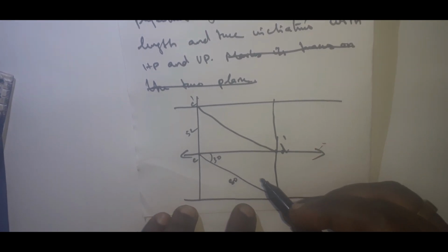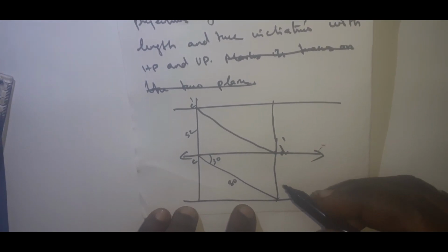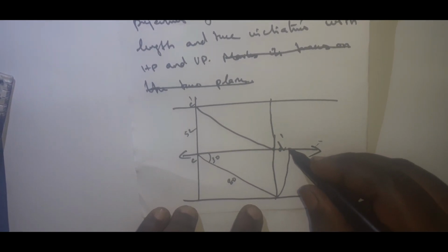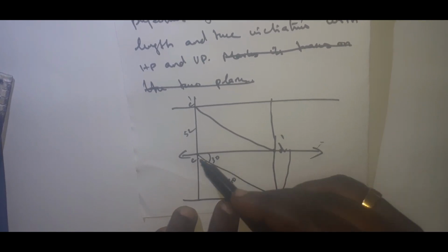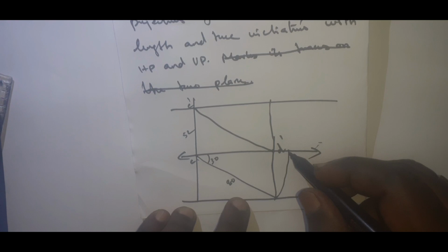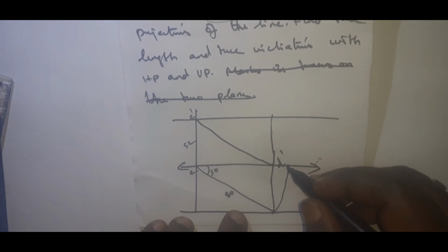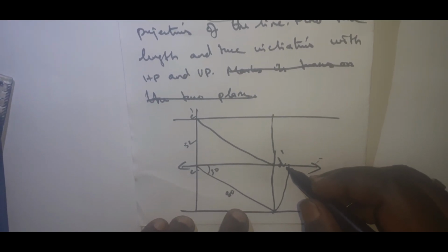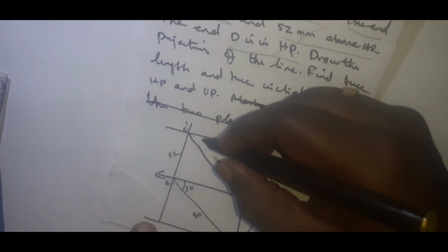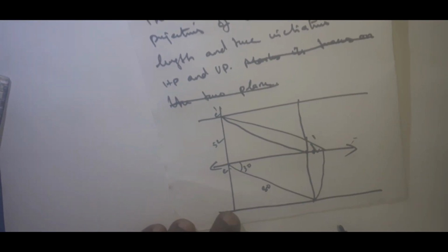Next, once the view line is given, we can start with an arc, then a straight line. So first arc is to the same starting point locus. Keeping this as a center and this distance as radius, we can draw the arc to the same starting point locus and to the next view's endpoint locus. Which one is the next view endpoint locus? The same point itself here in this problem. So we can connect. So here this will be the true length.